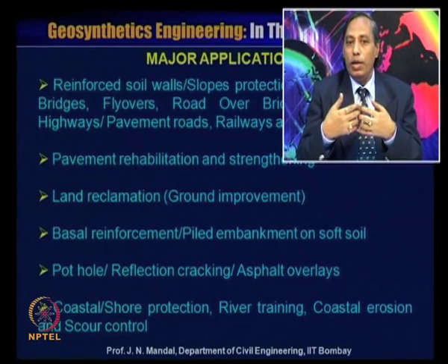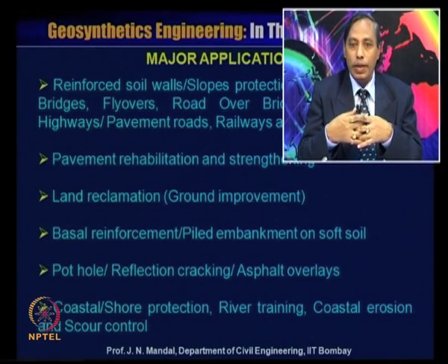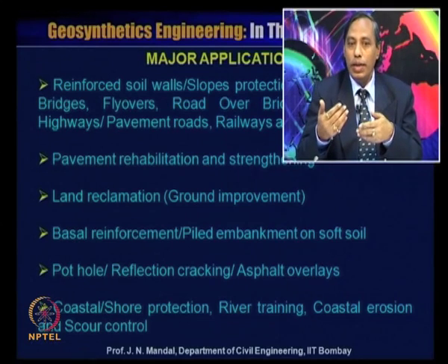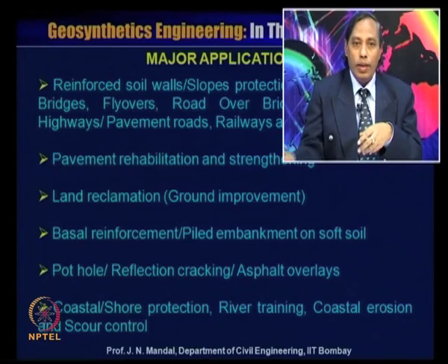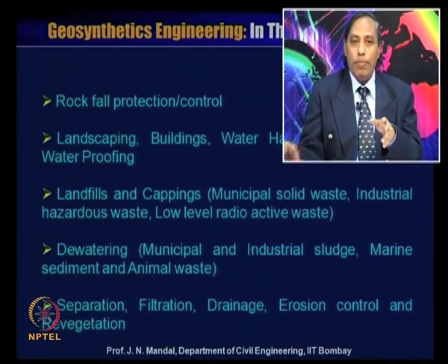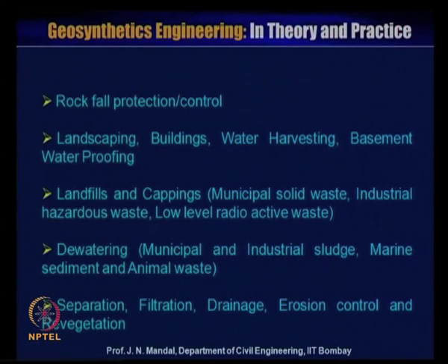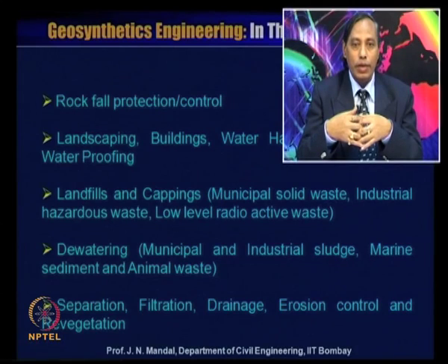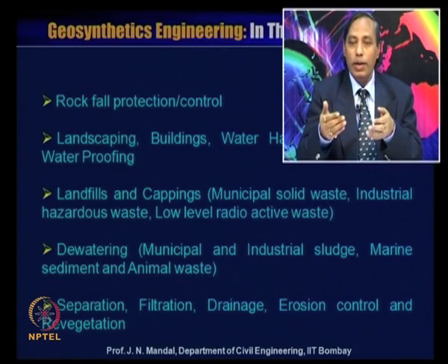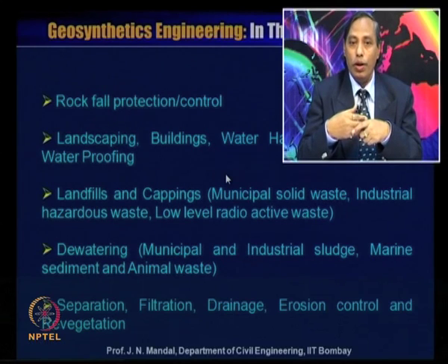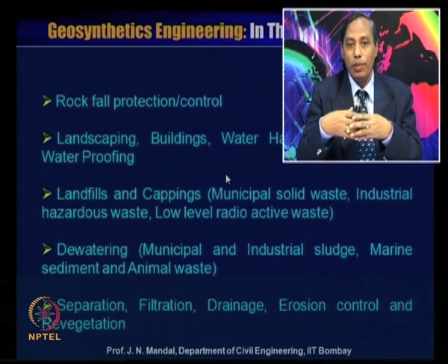This material can also be used for coastal shore protection, river training, coastal erosion and scour control. These are some of the major applications: rock fall protection control, landscaping, building, water harvesting, basement waterproofing, landfill and capping, municipal solid waste, industrial hazardous waste and even low level radioactive waste. It has been used also for low level radioactive waste, and its longevity is about 500 years.